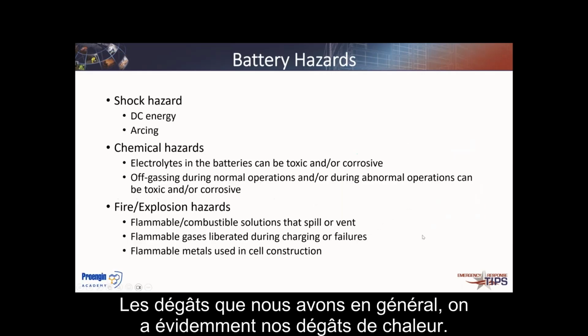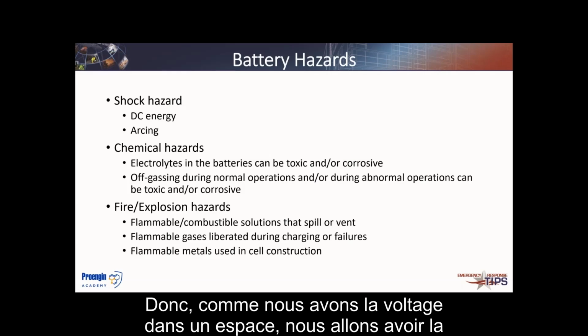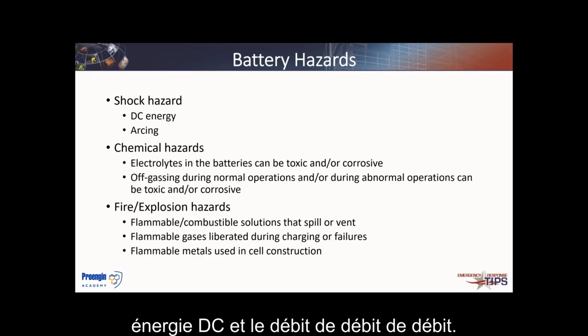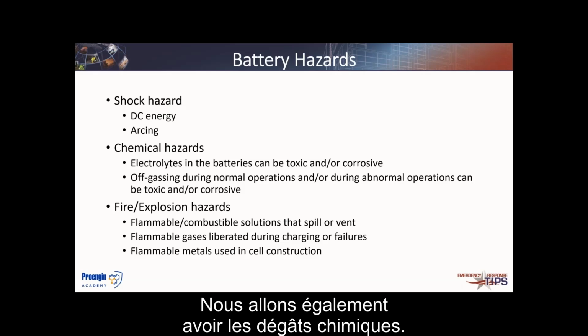Now, the hazards that we're generally looking at, we've obviously got our shock hazards. So as we have voltage in a small space, we are going to have the DC energy and any arcing that could come with it. We're also going to have the chemical hazards.